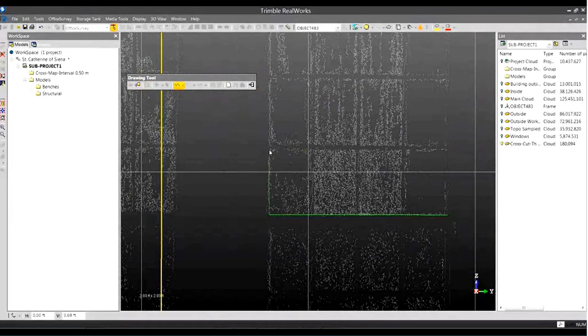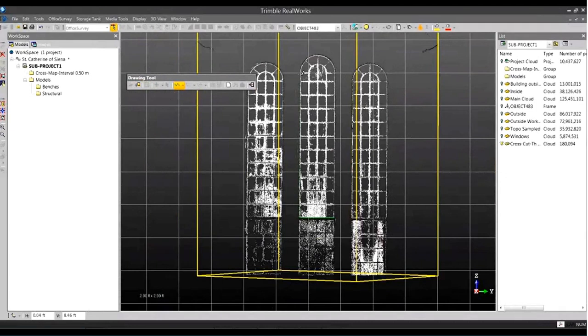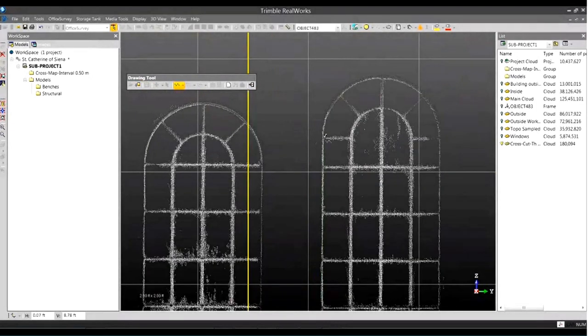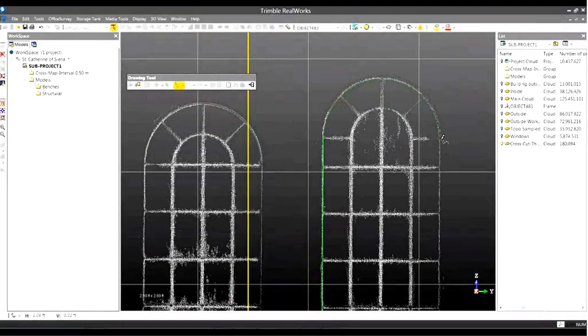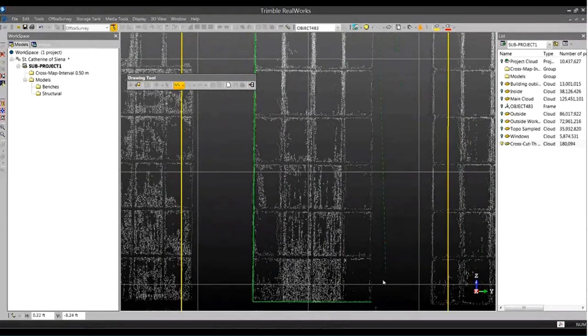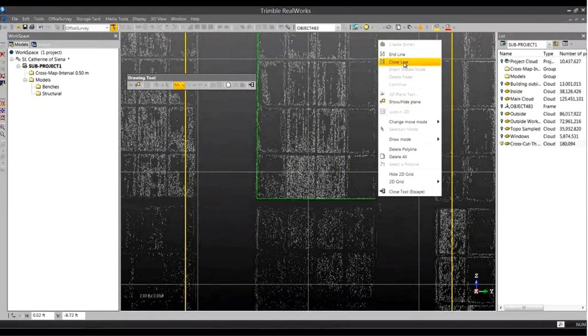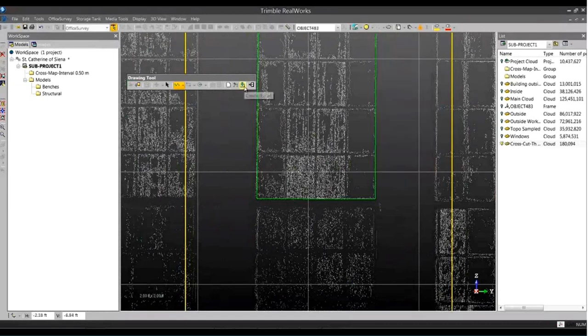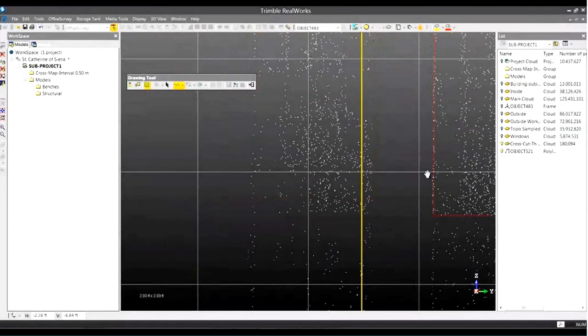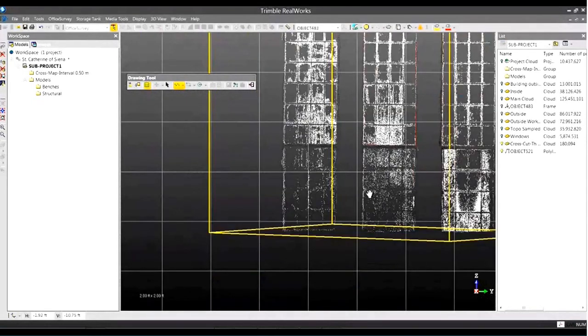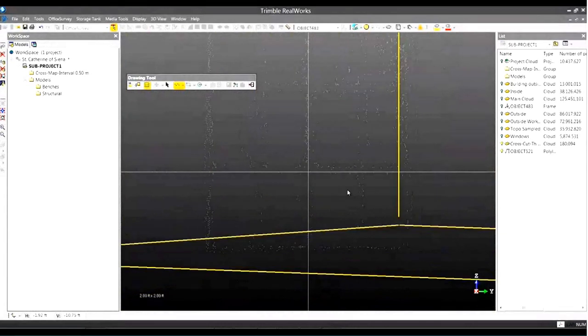I've got a few options. I can draw lines, rectangles, curves. Okay, I'm just using shortcut keys to switch to curves or arcs. And back to my straight lines. Just going to right click, choose to close this line, and create that. And you'll see the line now showed up over as Object 521 in my list window. Draw these other 2 windows.